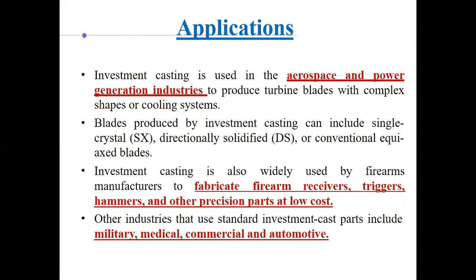The properties of the casting depend on how it's solidified, the grain structure. So if you are able to manipulate the grain structure with directional solidification, then that is a very good achievement. Directional solidification will get you enhanced properties, which are required for strength purposes. So those can be done.